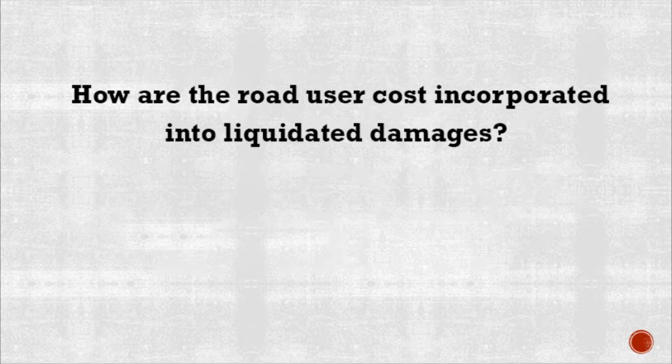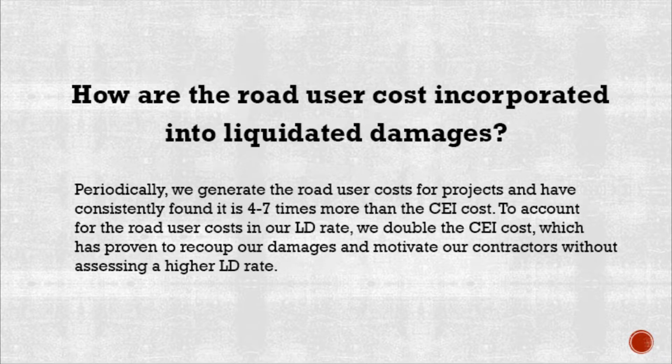How are road user costs incorporated into liquidated damages? Periodically, we generate the road user cost for projects and have consistently found it is 4 to 7 times more than the CEI cost. To account for the road user cost in our LD rate, we doubled the CEI cost, which has proven to recoup our damages and motivate our contractors without assessing a higher LD rate.